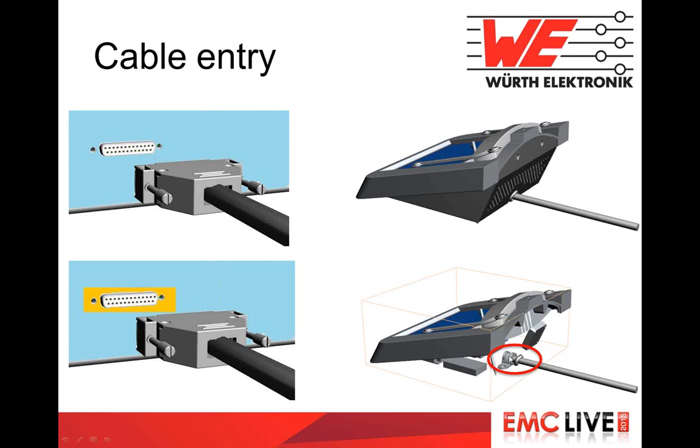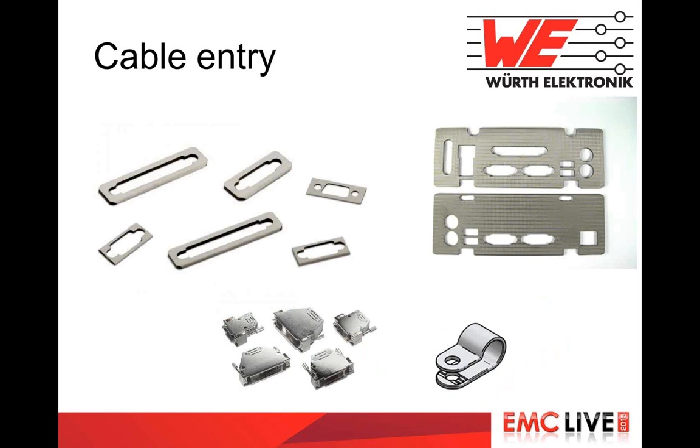When we use a pass-through cable, for example, a grounding clip or an EMC gland will help us to connect the 360 degree shield with the ground of the PCB or to the enclosure. So these simple solutions will solve one of the biggest problems we can have. As I told you, there are many possibilities: conductive foam, stamped conductive gaskets. It is also important, when you use connectors, that these connectors are shielded, because if you have the shield arriving to your connector and then you do this pigtail inside your connector, you have the same problem. So it's important to use shielded connectors and ground clips. Always try not to leave any discontinuity between the shield of your cable and the shield of your enclosure.